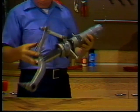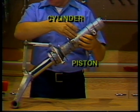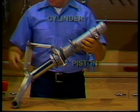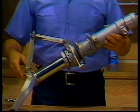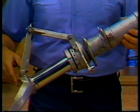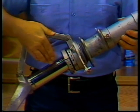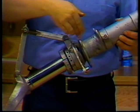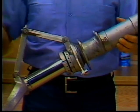The outer tube is referred to as the cylinder, and the inner tube is called the piston. The cylinder and the piston, when assembled, form an upper and lower chamber for the movement of fluid. The lower chamber is always filled with hydraulic fluid, while the upper chamber contains compressed air or an inert gas, usually nitrogen.